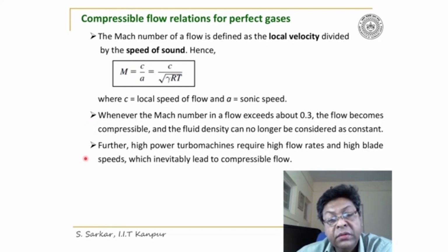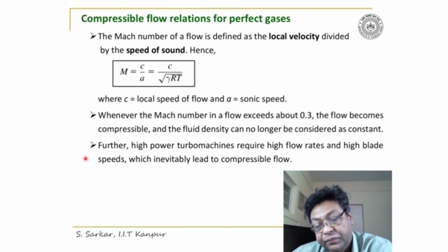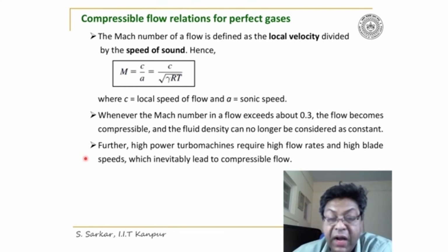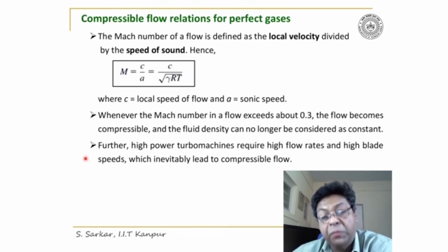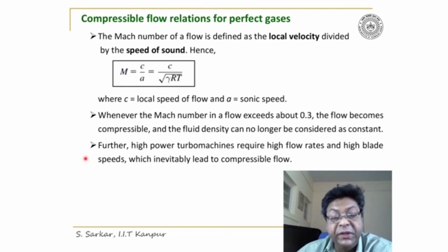Furthermore, high power turbomachinery requires high flow rates and high blade speeds, which invariably leads to compressibility. So for compressors or turbines of high power and speed, the flow must be treated as compressible.